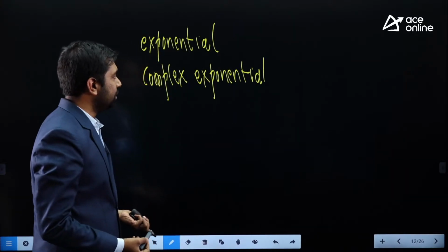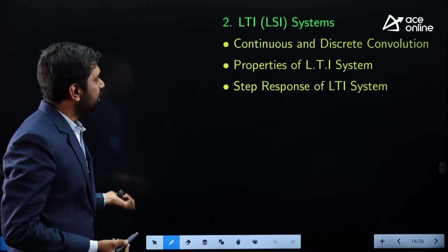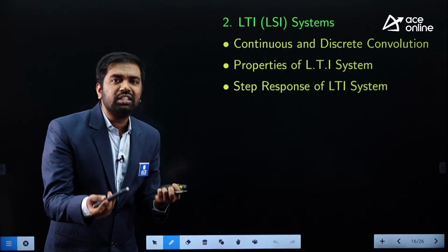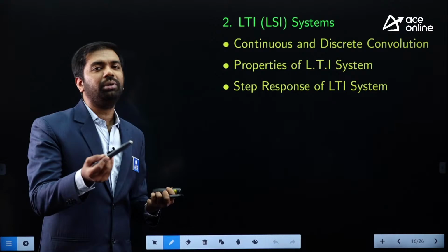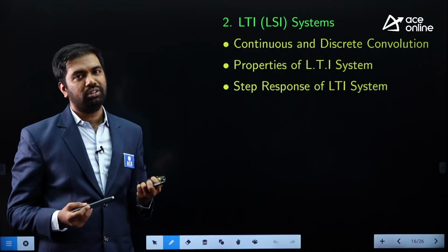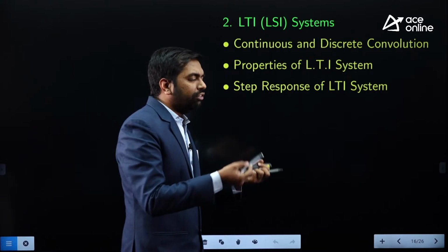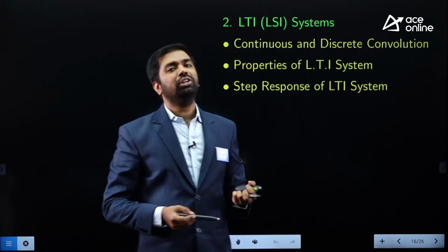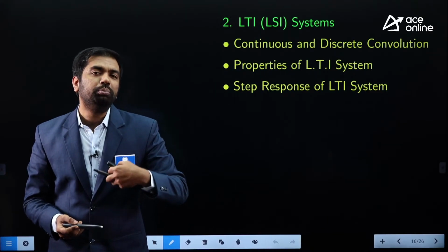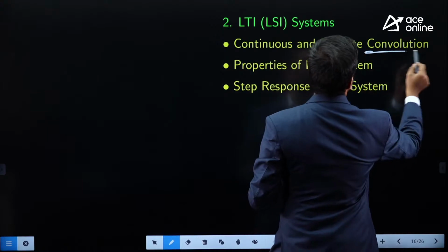Let's move on to the next topic, that is linear time invariant systems. Let's look at LTI systems. What does LTI stand for? It stands for linear time invariant. If I give you an LTI system, how do you find the output response? It's a very, very important concept. If the input waveform and the impulse response waveform are given, you simply convolve these two waveforms to get the output response of an LTI system. So convolution is needed.